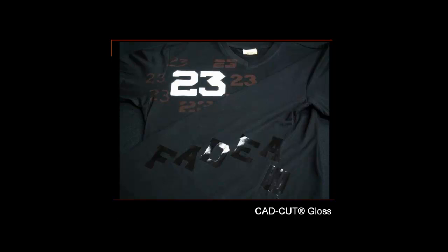And with heat transfer films, you can press them all at one time, or let's say you want to do a wraparound design or something that's a little large format, like say a tent or an awning, something like that. You can actually break up the pressing areas into sections on your heat press, as long as each area gets the recommended time, temperature, and pressure to reach the melting point of the adhesive. You can break it up into sections and peel the backing away all at the end.